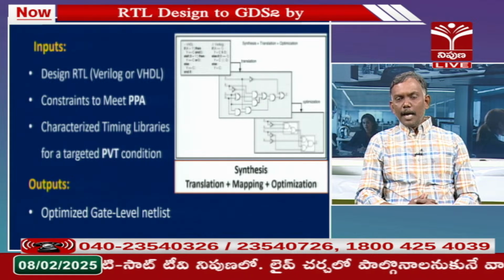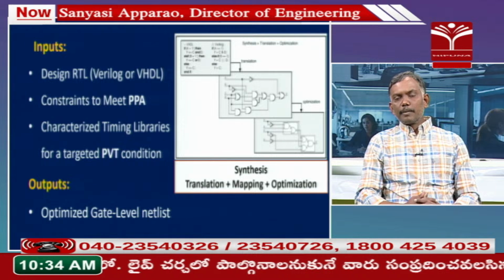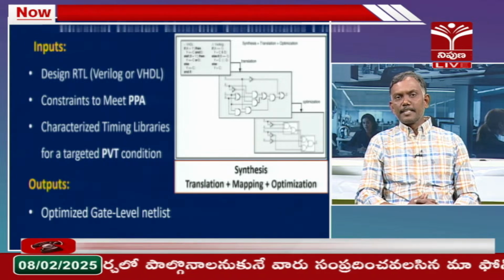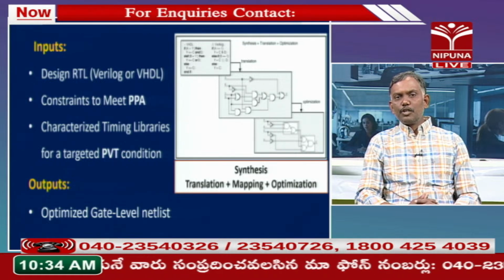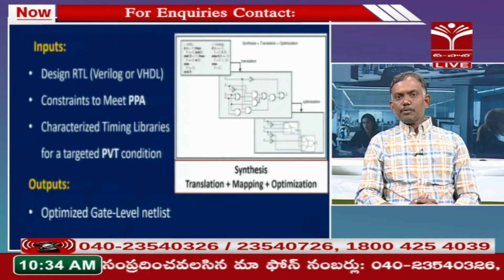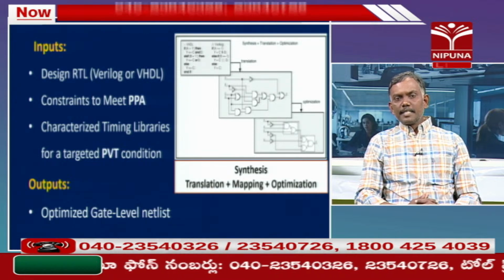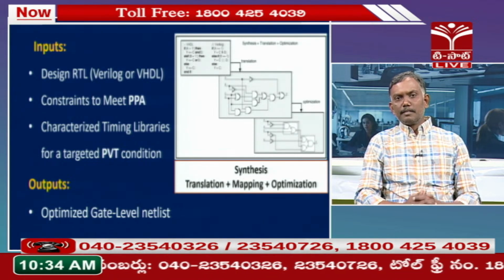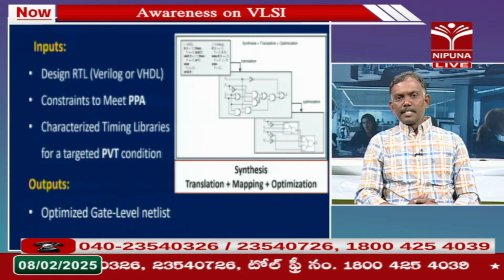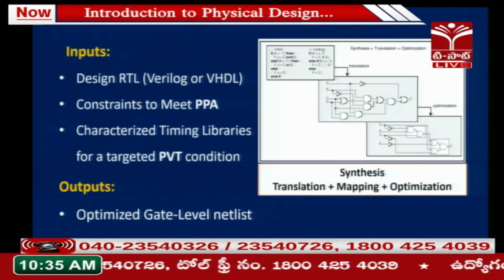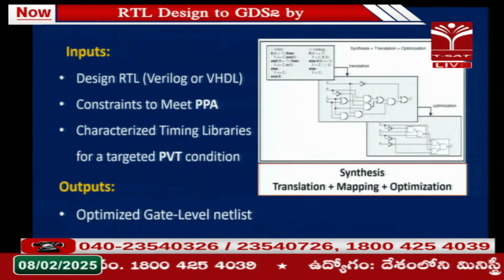Okay? As we discussed, the slow corner has more delays, the typical corner has certain delays, and the fast corner has fewer delays. Let us discuss this path B to Y. Let us assume, for understanding purposes, that each gate takes a uniform, common delay. Every gate takes 2 nanoseconds in the slow corner for a given input transition and output load.